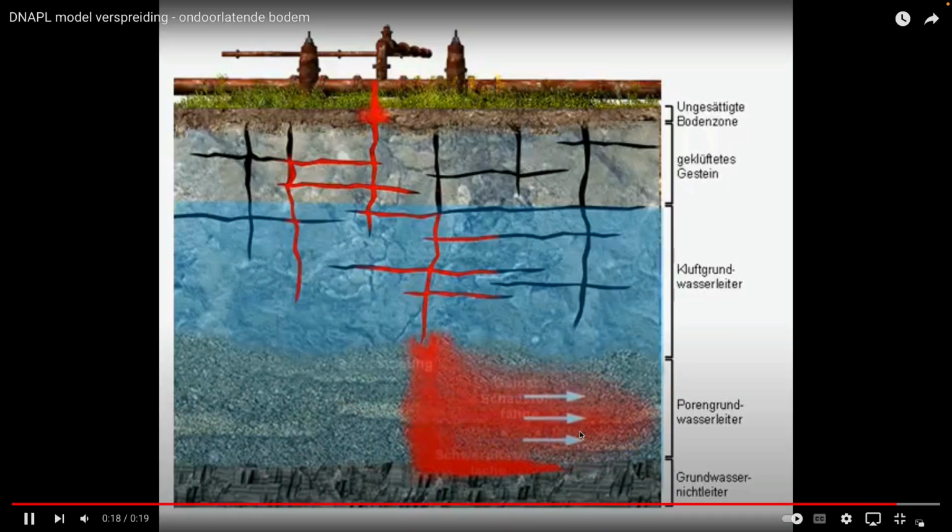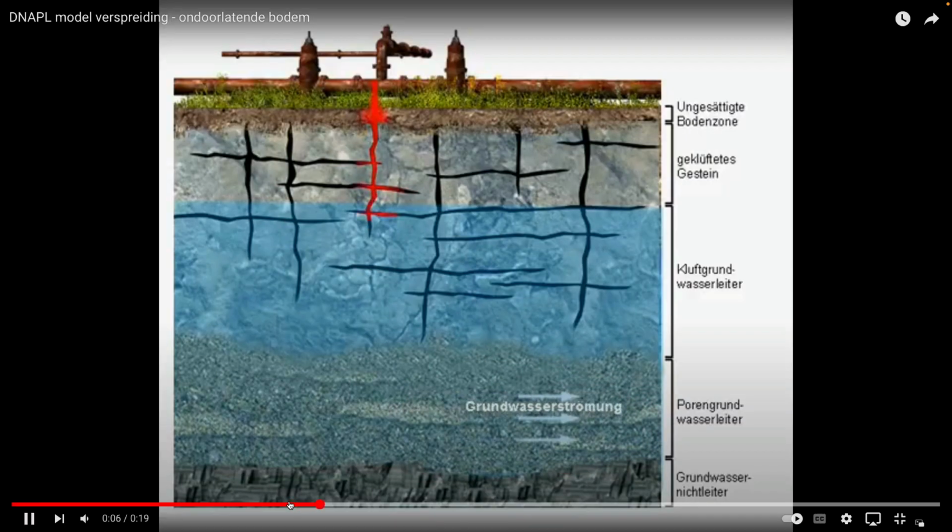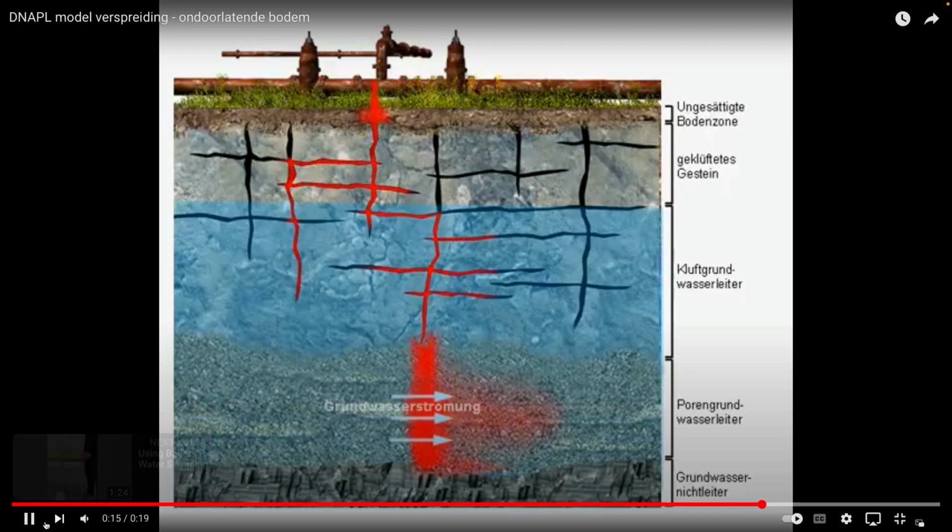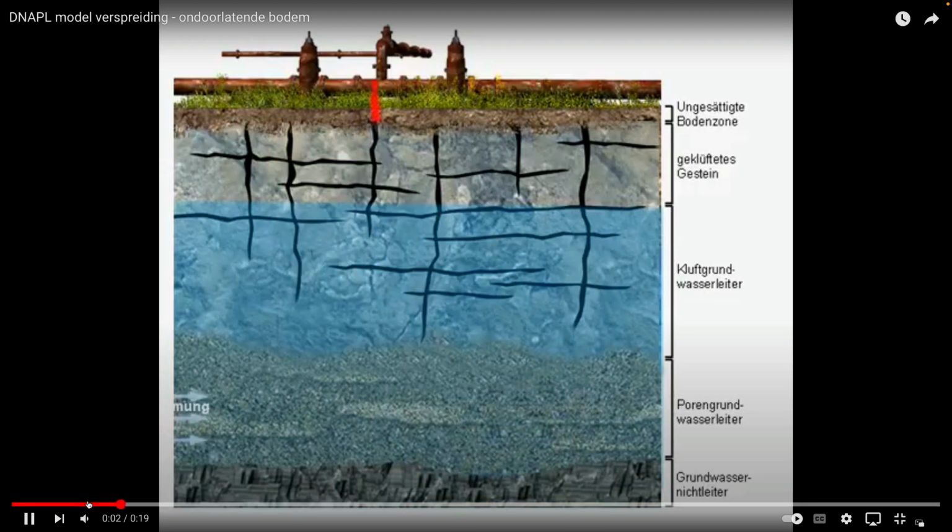And so they can act as superhighways, both being able to get into the subsurface much more easily because of the large apertures which might exist in fractures, and they can also travel quickly because the permeabilities of these are controlled by the aperture squared, we found out, just based on fluid mechanics arguments. So we know a fair bit about these materials.